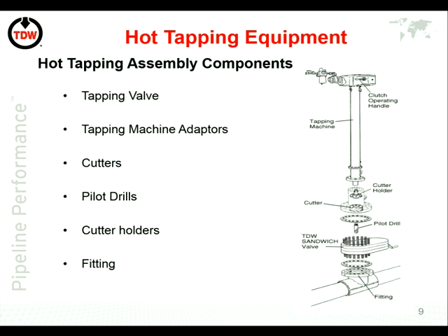Sandwich valve, the term sandwich valve, it's an isolating valve. The reason it's called a sandwich valve is it's very thin. So we think of a sandwich, two slices of bread with something in between, whether it be cheese or meat. The valve itself is the meat, and it slides in and out. The reason it's thin is just to save space, because this can stack up to be quite a height. And it's a temporary fitting. It's not generally classed as a permanent fitting on the line.